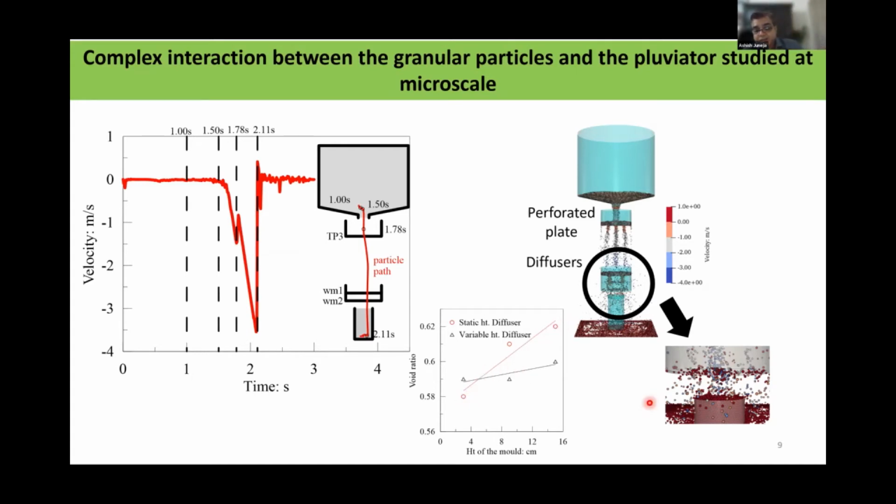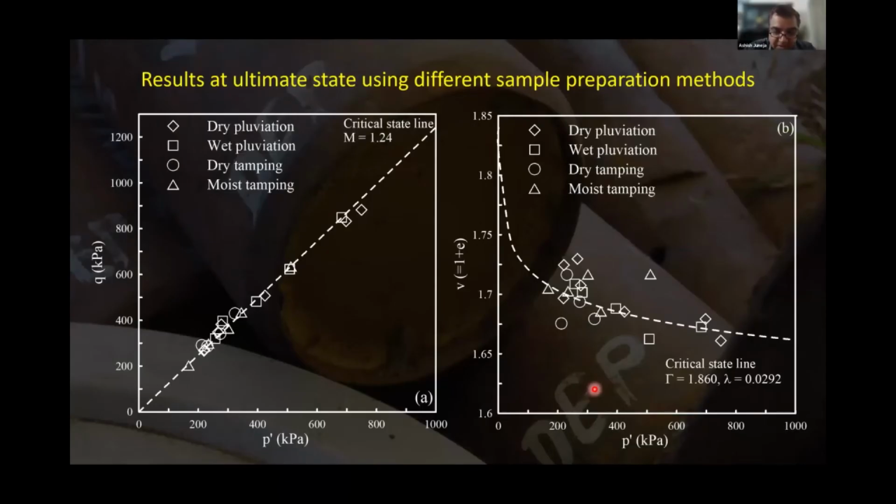The other one, which is more like static, you see there is a difference in the void ratio. These small values, of course, will play a role whenever we need to explain some kind of background. These do help in understanding why my soil has behaved in such a way. But having said that, what you see is the ultimate state, that means the friction angle at its ultimate state. That's the first figure.